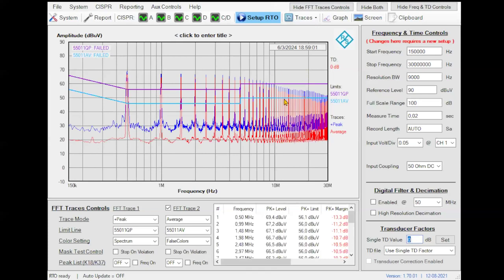Okay, so you see the reflections here are reduced. This is very important. If not, you will start to see peaks that are not from your device, peaks created by your setup. Well, so what can you do to reduce these emissions? What you can do basically is to review the design and to try to minimize these emissions. The good strategy is not to introduce a filter. The best strategy is to try to switch slower, considering efficiency, perhaps to introduce a spread spectrum if possible.